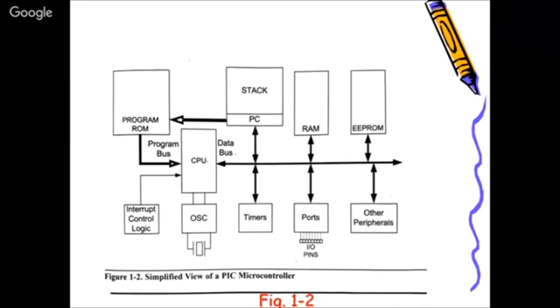What happens in this Harvard architecture, which is the case in the PIC controller, is that there are separate data and instruction set buses. So there are separate buses to fetch from your RAM memory and ROM memory. They are not a single or common bus system, which is the case in the von Neumann or Princeton architecture. In case of PIC, there are separate data buses and instruction set buses, and as a result the performance is very good.